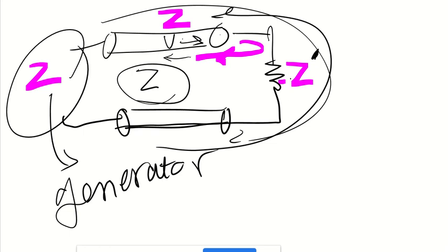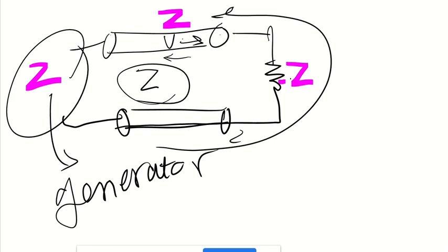But if the impedances are all the same and matched, that's actually good because I'm not wasting any power. That's why when you buy a coaxial cable and look at the impedance, it's important that it matches, for example, your receiver.